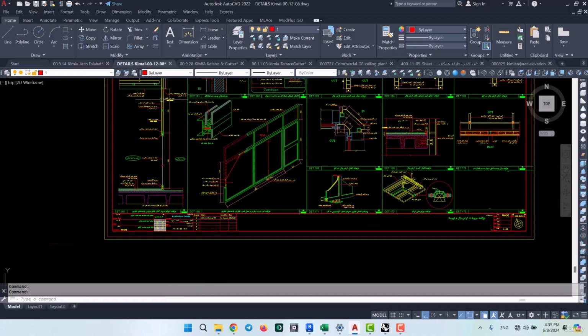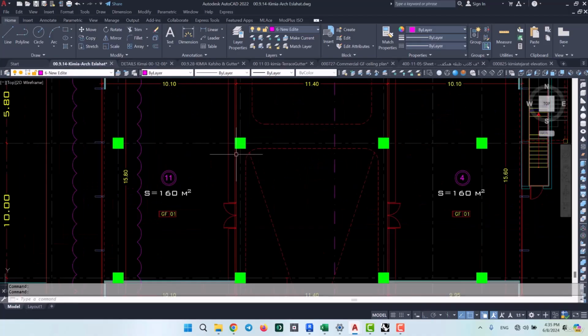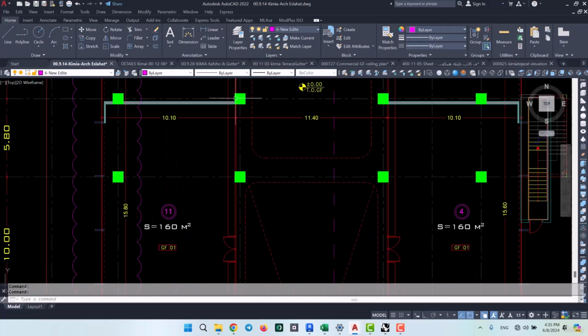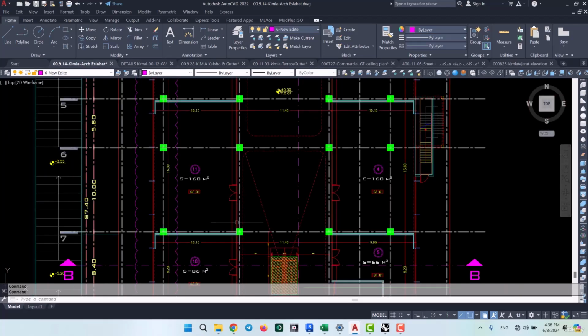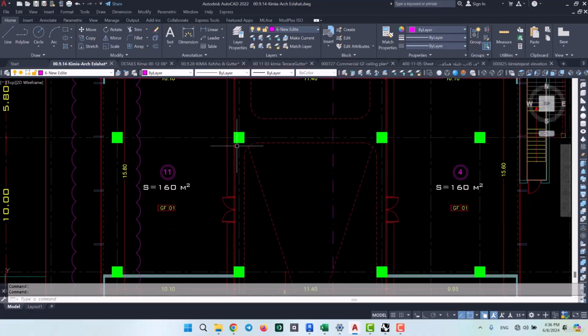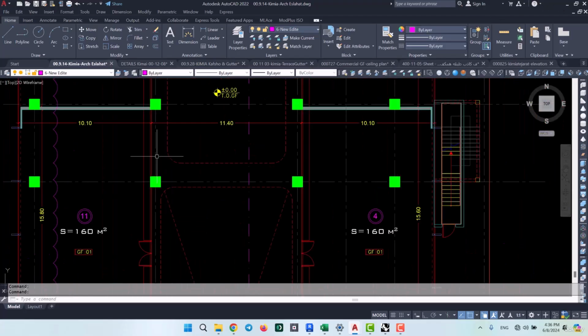And as for some other things that we had to ask the client, because we didn't have enough information as to what needs to be done in the file that they gave to us, eventually what was decided to be done for the service areas was that from the start all the way to the end, as well as in between for the doors, was to be a vertical constraint. So like we needed to have vertical mullions, and the horizontal mullions would have to go all over the doors. That was going to be in the same size and dimensions that we talked about. So far we've got some details for this part, which is that we need to place 4 centimeter mullions.